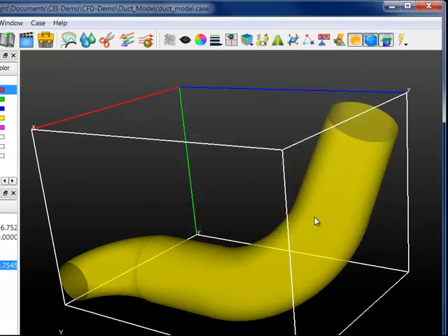So we'll hit OK. EnSight's going to use a structured volume rendering technique now. We're first going to map the data from our unstructured model into a structured IJK, which has a resolution of 128 by 128 by 128. And then for that particular volume, we're going to render each element in that volume based off from its velocity.